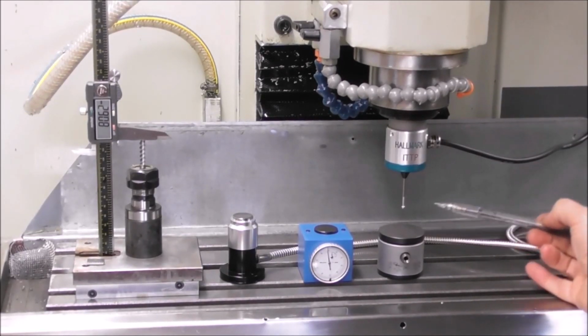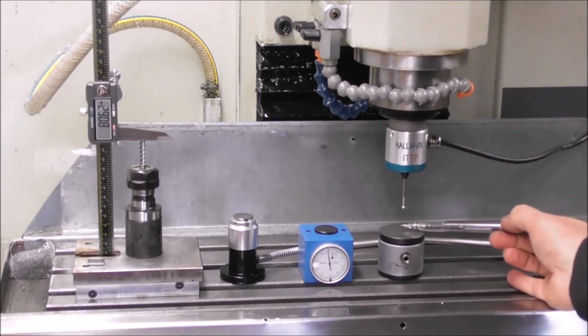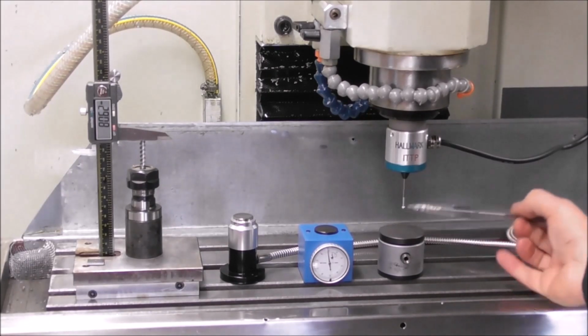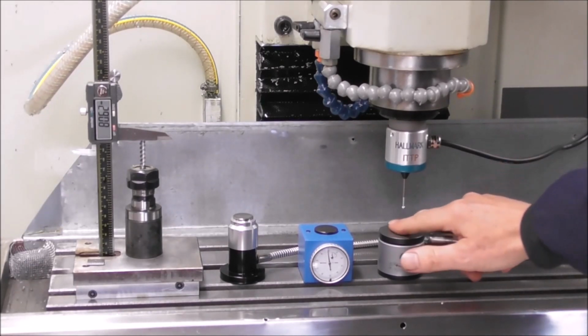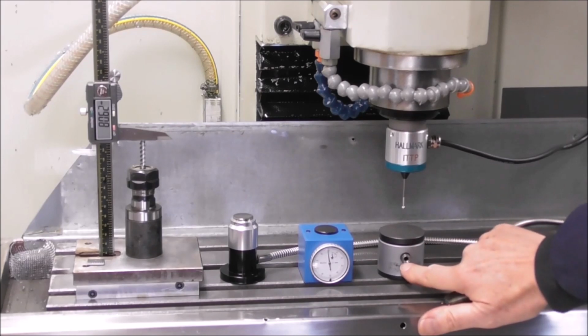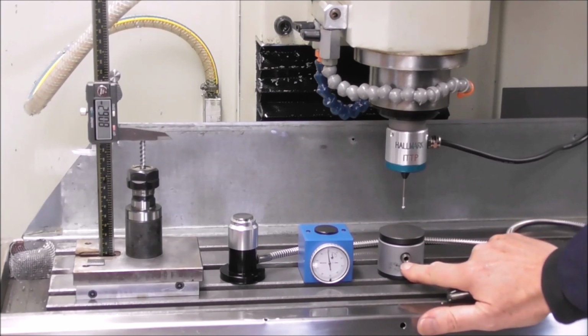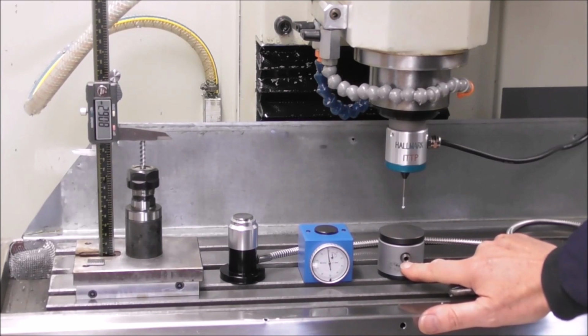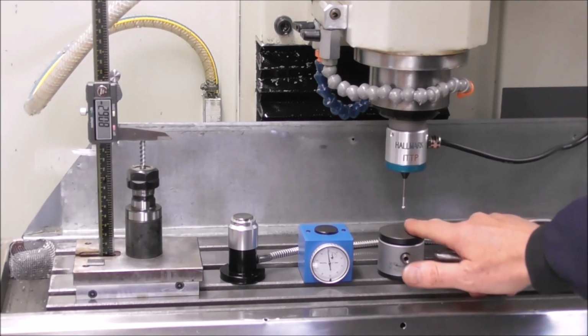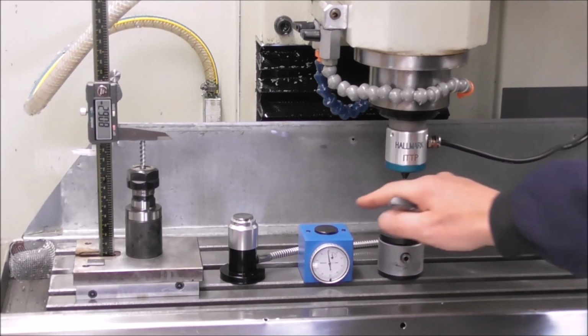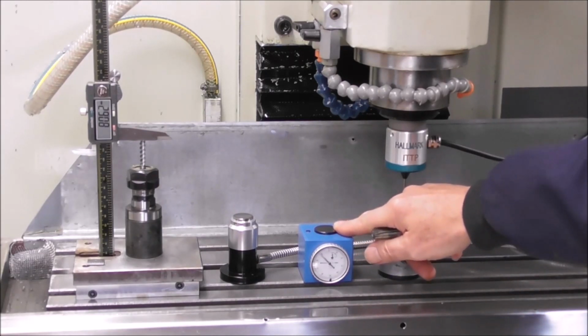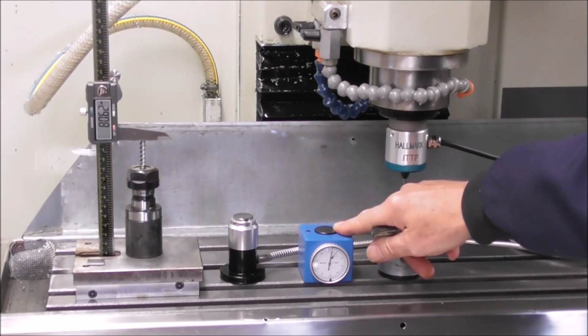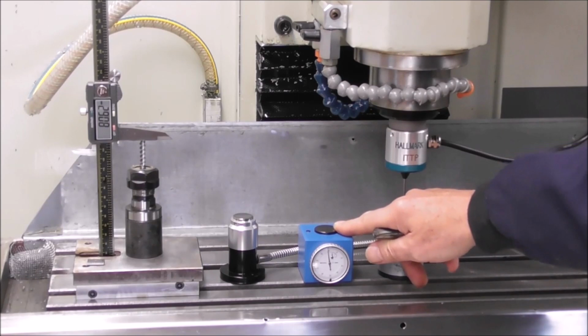Okay, so let's look at the different options for tool setting, tool length setting. Just a quick overview to start with. You can have a manual tool setter, which is a little spring-loaded surface and a little LED that comes on when it's reaching a critical point, and that becomes your reference point for setting all your tools when the little light comes on. You can have a dial indicator type, so when the needle strikes 0, that's an exact height or surface that you can set all your tools to.